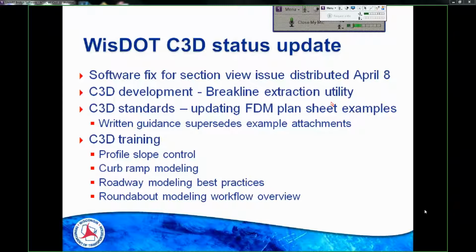The idea being that the designers ought to be able to pick out which curb ramps are going to be a challenge to construct because of the elevations and the surrounding terrain, and which curb ramps will be a slam dunk and won't be a problem at all. And then the designer can depict those difficult curb ramps and include them in the design model deliveries. But it takes time to model each curb ramp, so we only wanted to have that attention put where it was needed. So that's why they're optional.